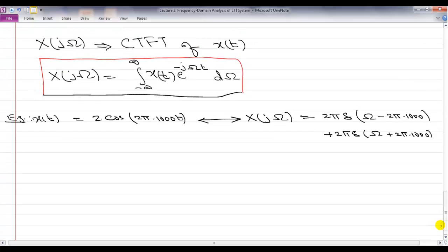So we are just trying to confirm that the Fourier transform tells us about the frequency. We start with a signal where we know what the frequencies are. This signal is a pure sinusoid and it has two components. If you think in terms of complex sinusoids, it has minus 1 kilohertz and 1 kilohertz frequencies present in it. Right? So this is the continuous time Fourier transform.